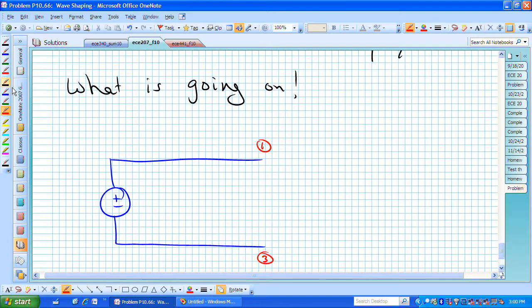But between node 3 and node 2 was a resistor. Let's say here's node 2, and if we go back, that was a 1K ohm resistor, and I'm going to call that R sub 3 since it's touching node 3. We also have a 1K ohm resistor between node 1 and node 2, and I'm going to call that R sub 2.